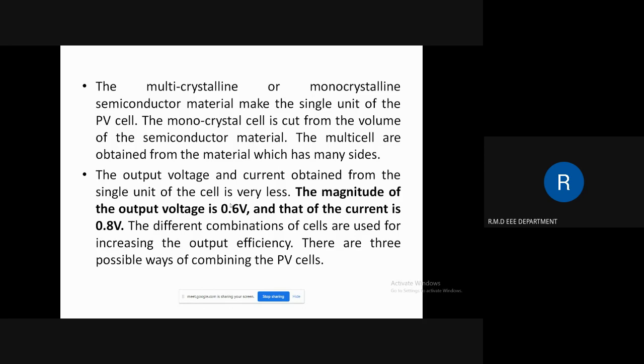The solar cell IV characteristics range from short circuit current ISC at 0 output volts to 0 current at the full open circuit voltage VOC. So the maximum voltage available from a cell is at open circuit and the maximum current at short circuit. Neither of these conditions generates any electric power, but there is a point in between where the solar cell generates maximum power. There is one particular combination of current and voltage for which the power reaches its maximum value, that is at the IMP and VMP values.